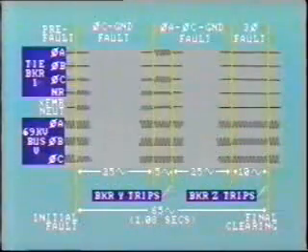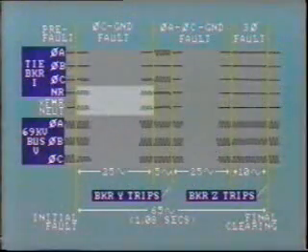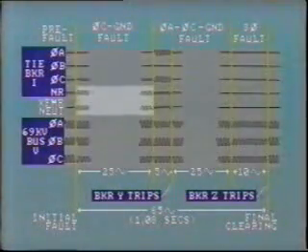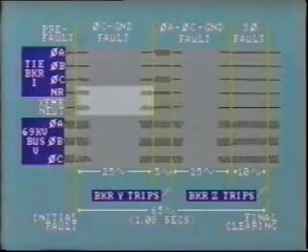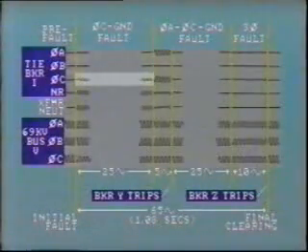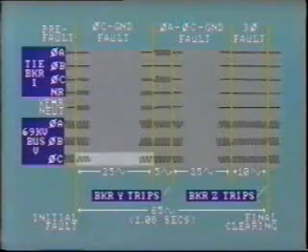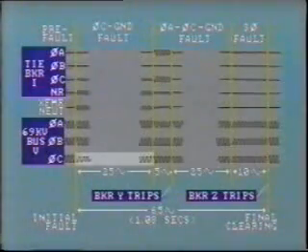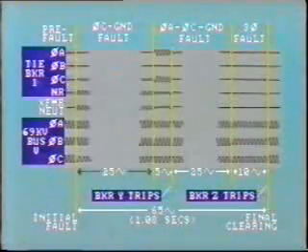This fault was actually caused by a tree falling across one of the phase conductors. The tree provides a path to ground. Looking at the oscillogram, the transformer neutral current and the tie breaker residual current both clearly show that the fault is line to ground. The high C-phase current in the tie breaker and the low C-phase bus voltage tell us which phase has been faulted. The single line-to-ground fault endures for 25 cycles.